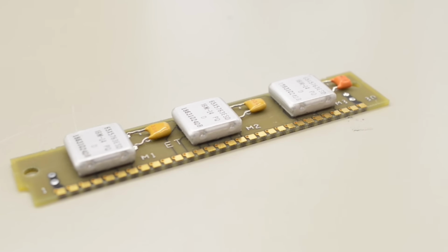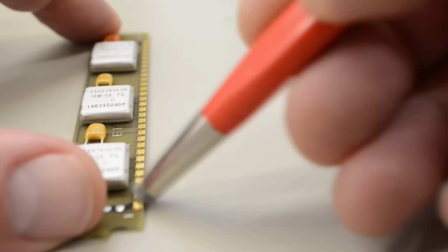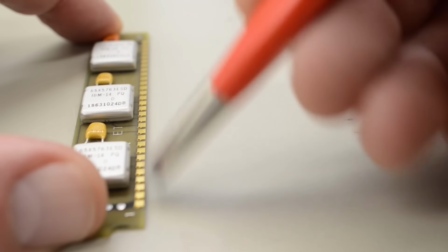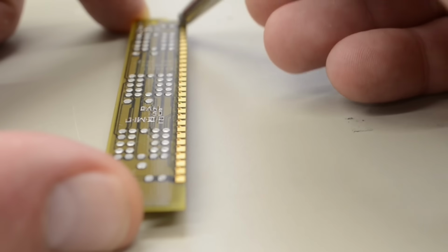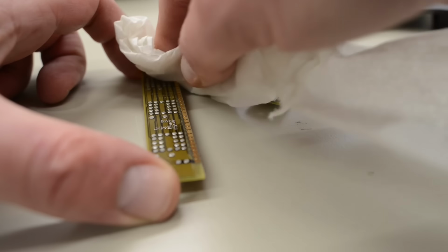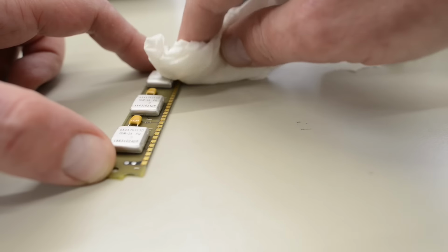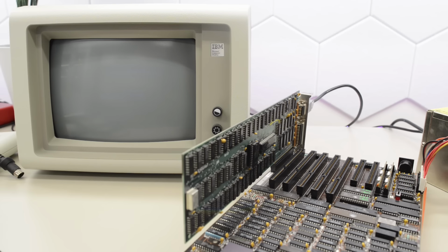One thing I didn't think to test was to try the board with these original SIMs after I had cleaned those slots. So let's just quickly clean these pads off and do a test. In case our board is picky with SIMs, I'll just use a scratchy pen and clean those pads off. Better wipe them with IPA, because that scratchy pen leaves tiny particles. Okay, the original SIMs reinstalled. And no, that didn't make a difference.